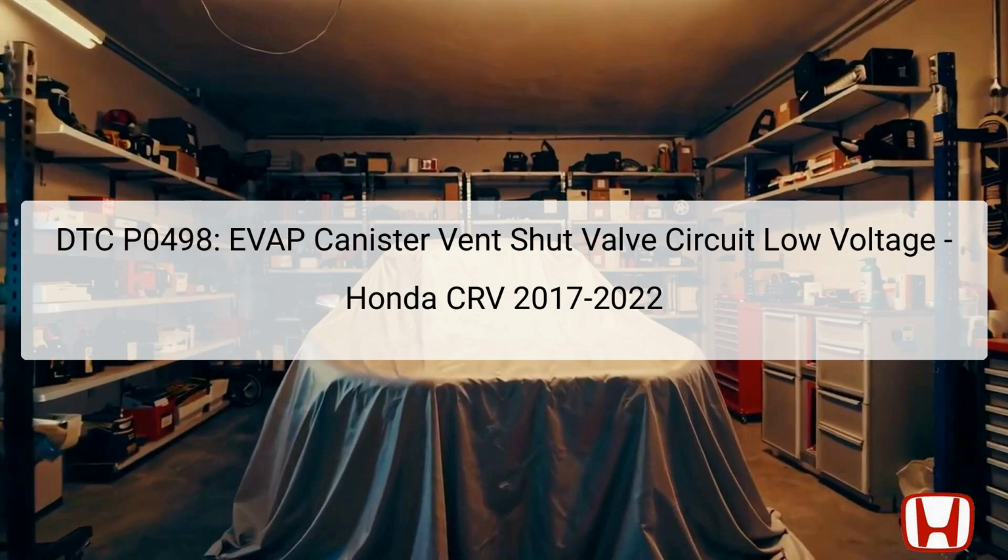The Diagnostic Trouble Code, DTC P0498, indicates a low voltage condition in the EVAP canister vent shut valve circuit of the Honda CRV between the model years 2017 and 2022. This code directly impacts the evaporation EVAP system, which is responsible for capturing and recycling fuel vapors from the fuel tank to prevent them from escaping into the atmosphere.